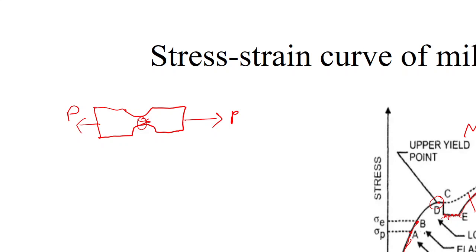No. See, actually, that's a kind of measure they can attribute to. But what is actually meant by ductility is how long it can permanently deform without any fracture. That is the measure of ductility. For example, in the mild steel stress strain curve, you can see that only at this point the material fractures. Whereas a brittle material, without showing any permanent deformation, fractures without giving any warning.